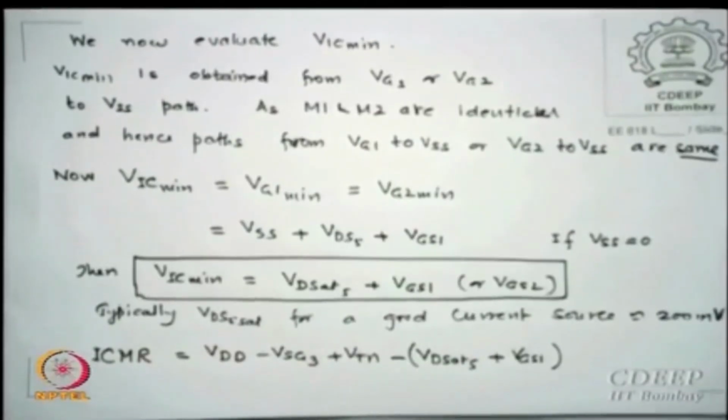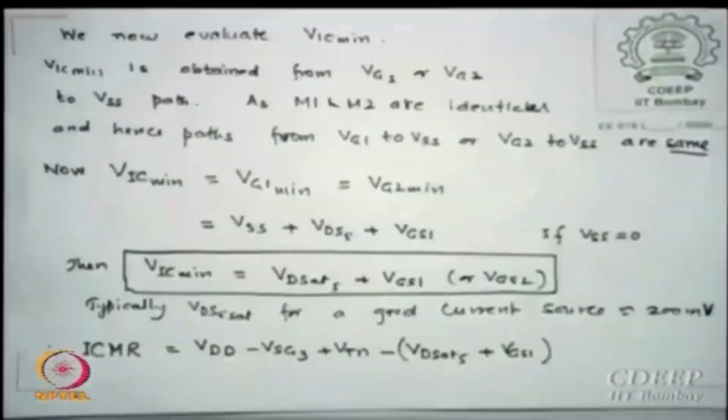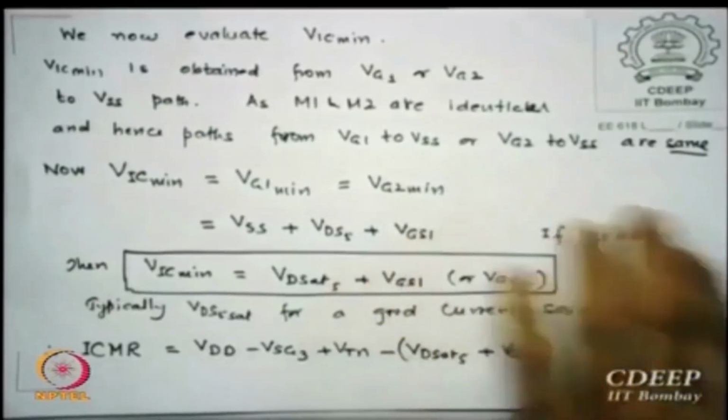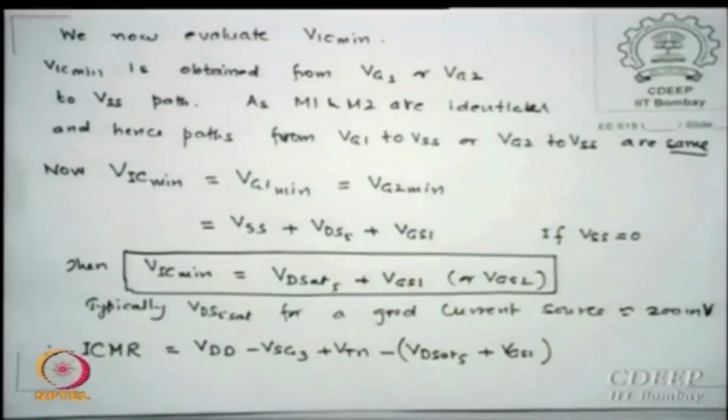Okay, is that point clear? This is a trick in designs, which spec is given and which you have to evaluate. Please remember this VSS is 0 is not a normal case. In most op amps you will always have dual rail, so you will have VDD 2.5 and VSS minus 2.5, swing still may be 5.